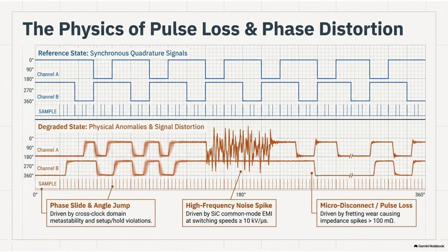The entire goal of this architecture, which is mandated by the ASIL D standard, is to identify and react to a fault within a strict fault-tolerant time interval. The FTTI. Yes, an FTTI of less than or equal to 60 milliseconds. 60 milliseconds. In that microscopic window, the car has to realize a sensor broke, figure out a backup plan, and actually execute it. It's incredibly fast.